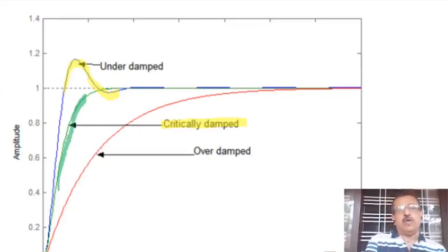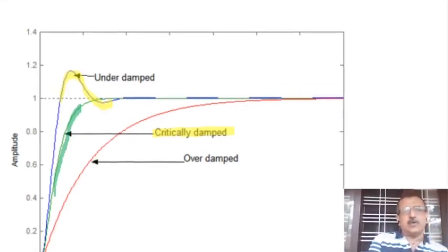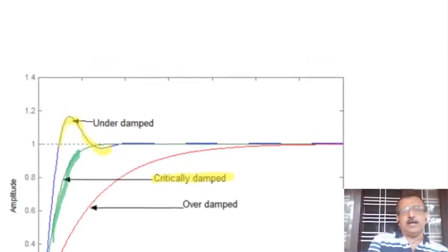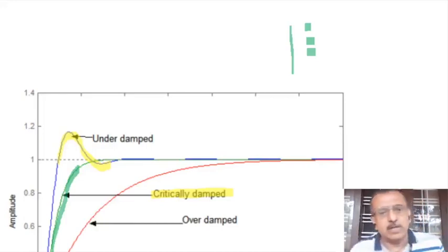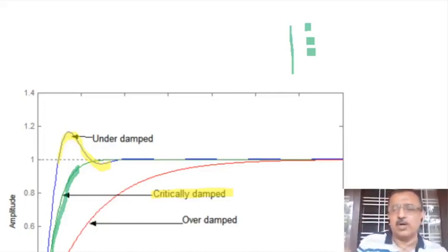Once you know the transfer function, you know omega n, and you could draw a table. You can write C(t) here, then corresponding time here, and you can compute all the values of C(t). You can write it in Excel and you can plot C(t) versus t. You will get this graph. I would recommend that you do it. Or if you know MATLAB, you can write a very one-line program, or in Python, whatever. I would recommend that you draw the plot.